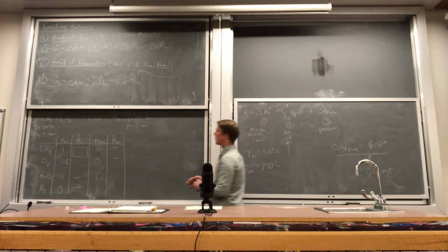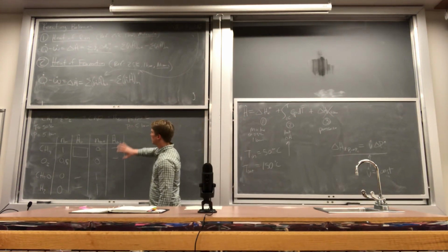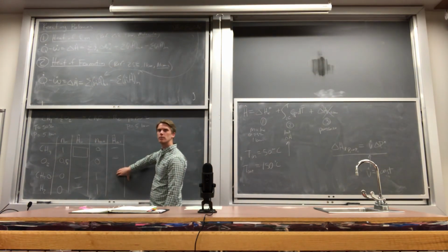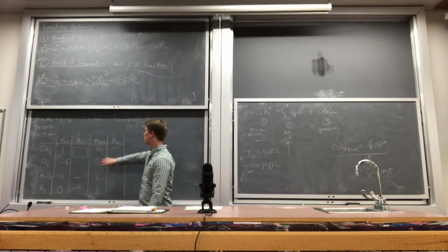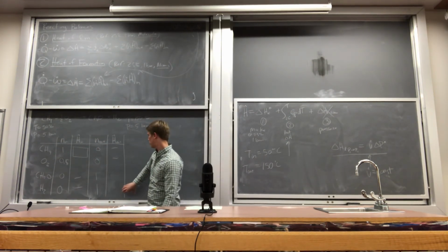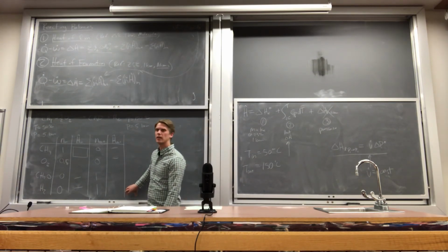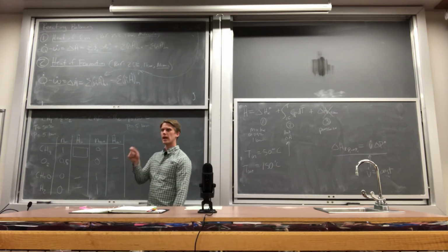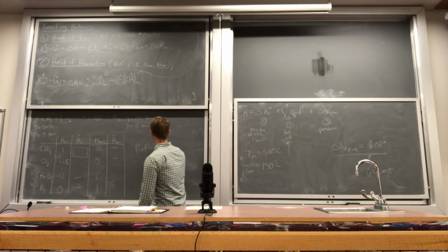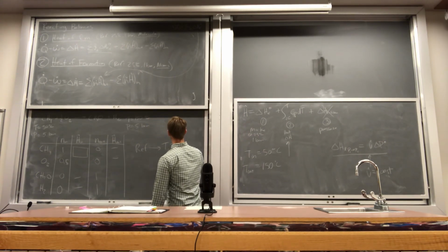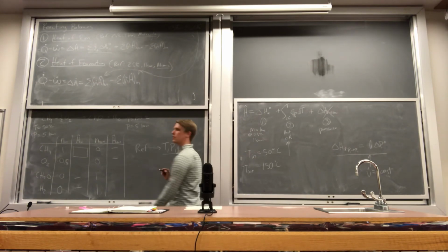All right, so I highly recommend the heat of formation approach for most all of the circumstances that we're going to be doing in the class. It's simple, it's algorithmic, there's no trickery. As long as you can do the material balance, then the energy balance is just a sort of busy work tacked on top of it. The only tricky part associated with any of these methods is keeping track of the pathway that you have to do going from your reference state to whatever the temperature, pressure, and phase of the reaction that's going on.